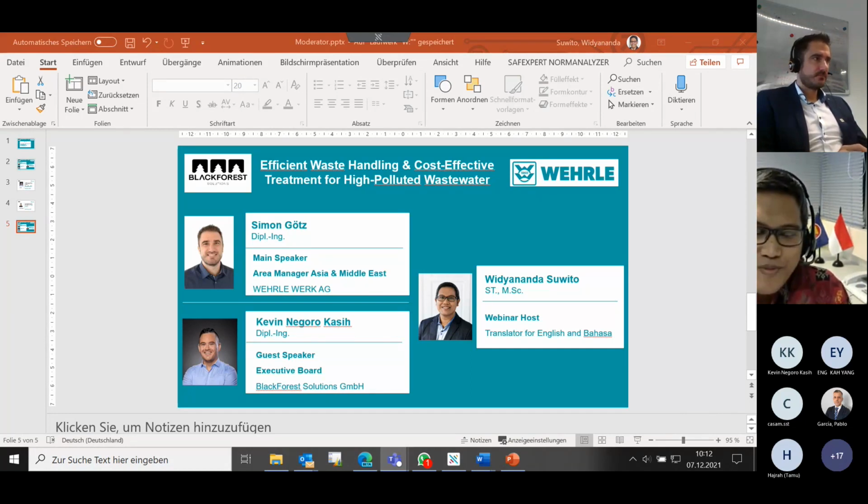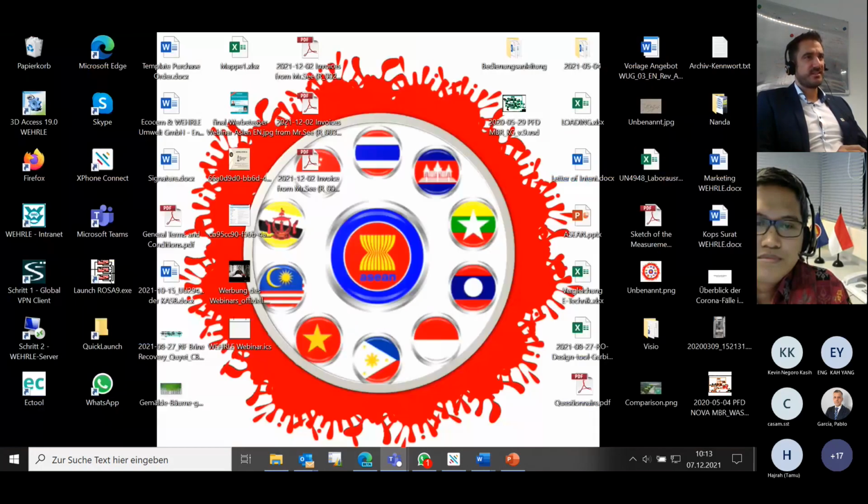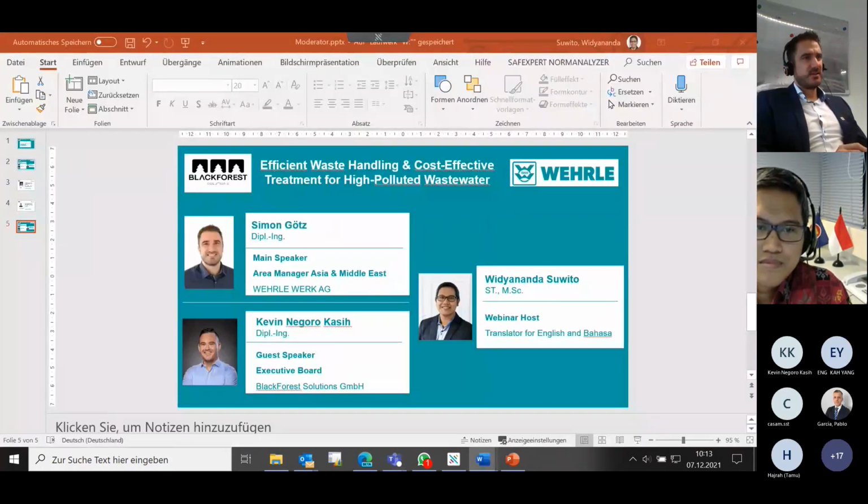The next question is coming from Mr. Pablo. Thank you again for the presentation. Could you explain the difference between the required pre-treatment for direct reverse osmosis and MBR biomembrane treatment? Yes, good question. Usually the direct RO needs a higher pre-treatment because the spiral wound elements cannot handle, for example, high concentrations of suspended solids (TSS), also not oil and grease, because that sits on the membrane and reduces the flux rate drastically, compared to a biomembrane system, which is extremely robust.